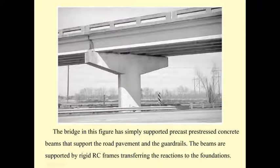After they lift them up, each of the beams will be put in place, and then a precast slab is put onto the top of the beam, and then some temperature wire and reinforcement are also put onto the surface of this bridge, and then the concrete is poured and leveled, and then we will have the superstructure to carry the traffic load.